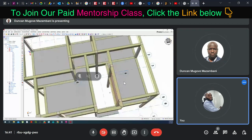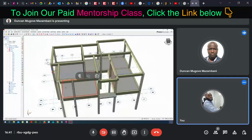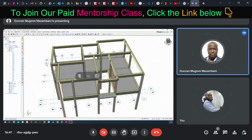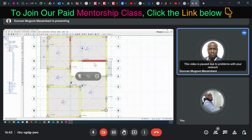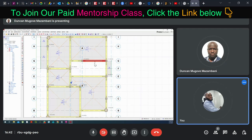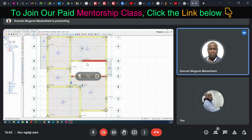Okay, now go back to your plan view and copy that wall load and paste on all the beams on the floor slab. Click on that beam, right click and say copy beam wall load. Have you done that?